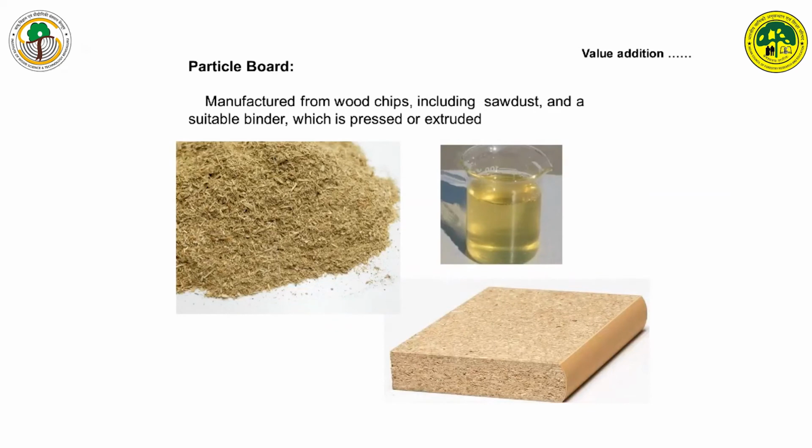Similarly, in the case of particle board, we go a little bit further in the degradation of the primary timbers. Like we go for dust, making the wood into particles, and again bind with the help of a resin. You bind it and press it to get a product of desired size. However, they are not structural. They are not meant for structural applications, but for some semi-structural applications, they are mostly utilized.